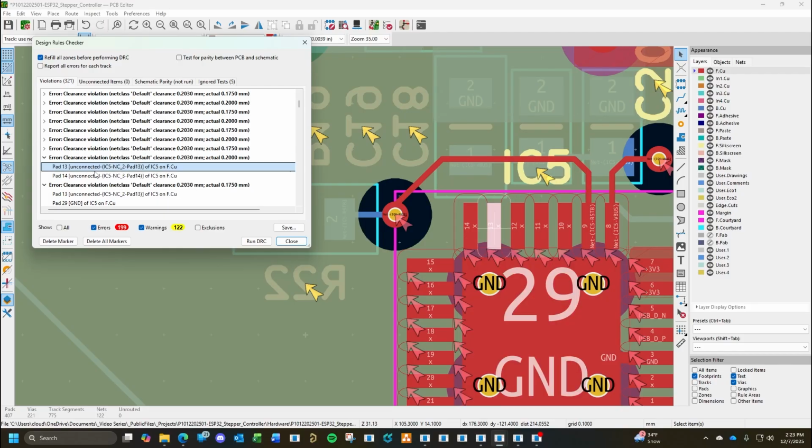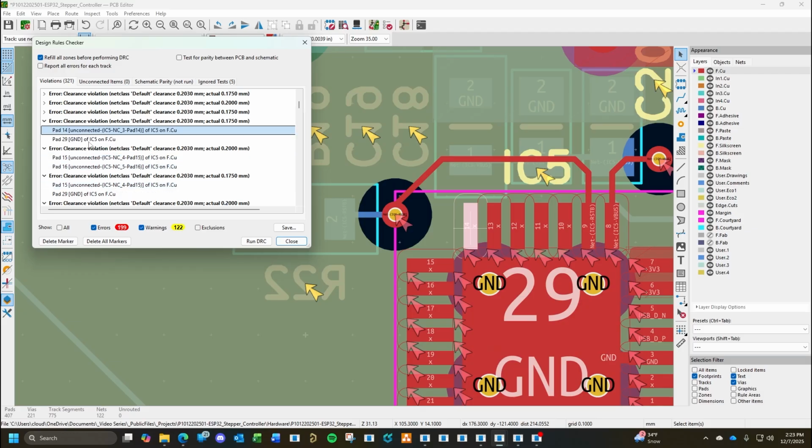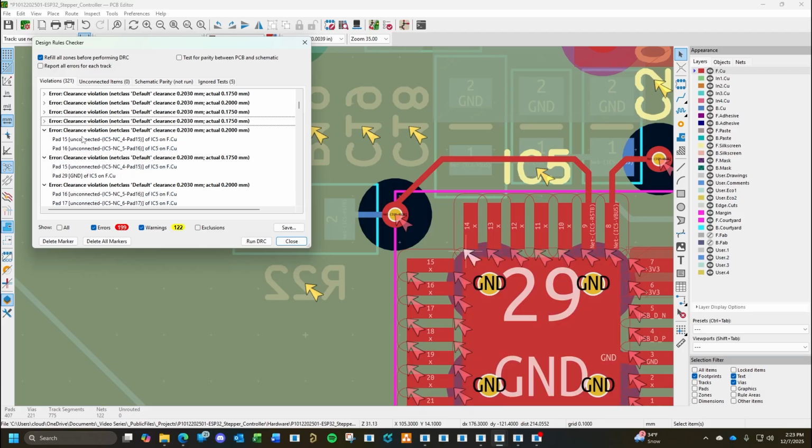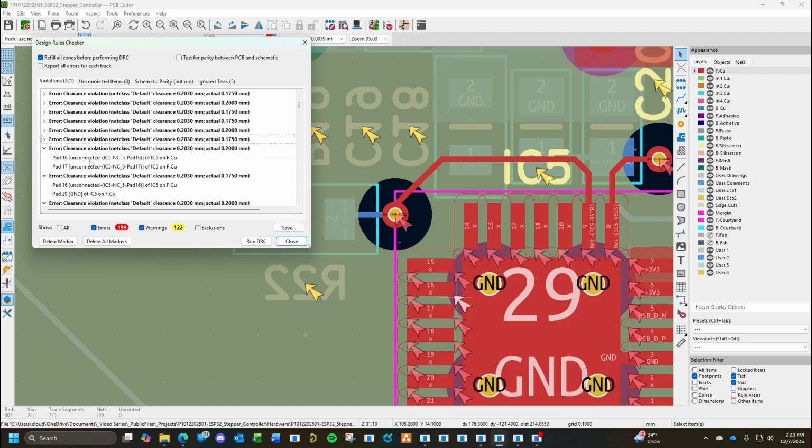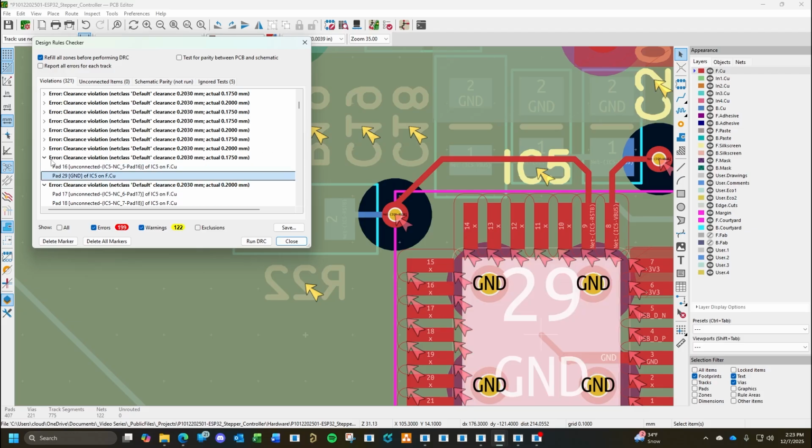Yeah. I just want to make sure that we don't have stray material, a stray line shorting things out, a piece of trace that we forgot to delete or move around, or something accidentally dragged isn't going to short anything out. Wow, this is really between these two, and then between that one and ground.